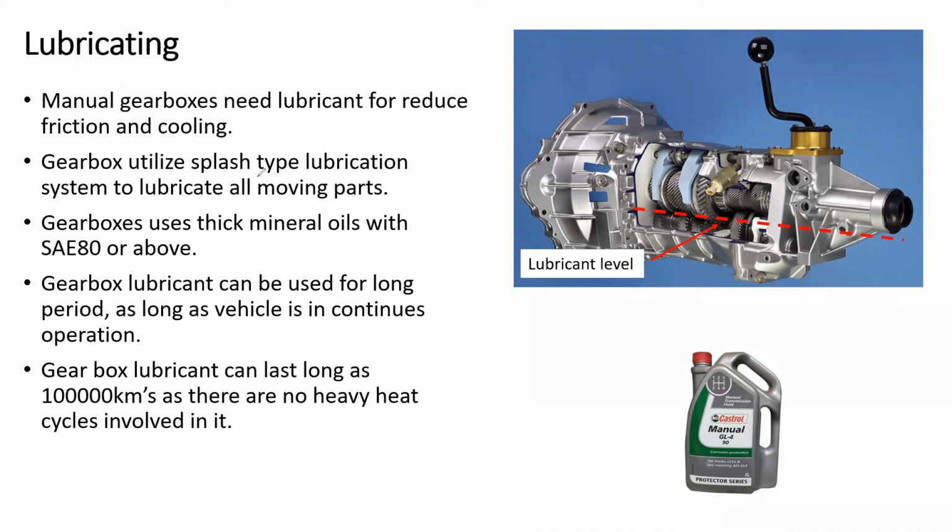Gearboxes like this, which use manual transmission, use what we call a splash type lubrication system. They don't have a pump supplying the lubrication unless it's necessary.